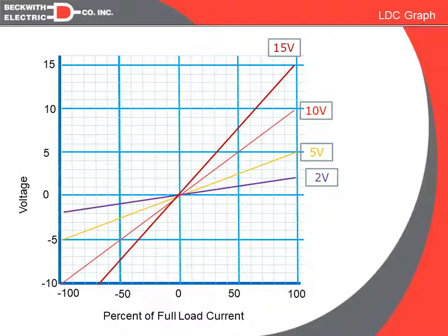So in the forward direction, a positive R or positive X will bias the regulator to want to raise the voltage more. But in the reverse mode, a positive R or positive X will encourage it to lower the voltage.